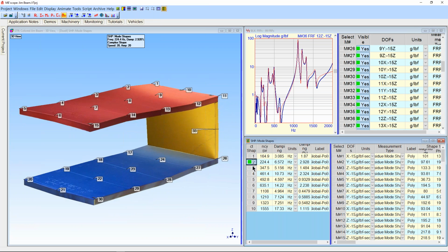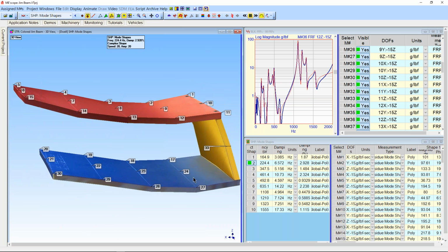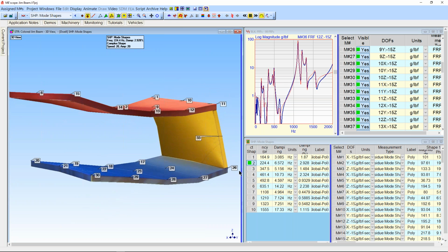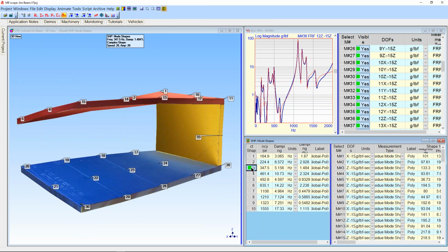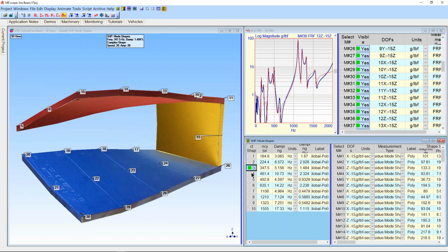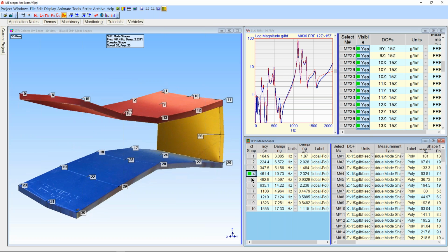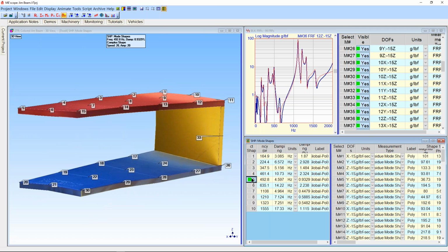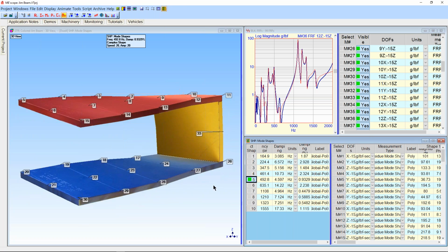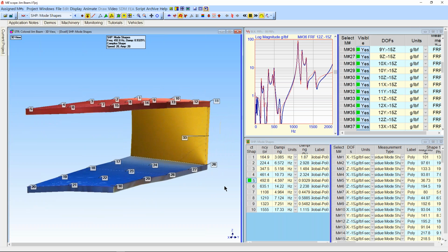And then bending, what I would call in-phase bending, where the top and bottom, I'm looking at first bending of both top and bottom. There's out-of-phase torsion. There's out-of-phase bending. So we can give these names, but pretty soon we run out of names. So the best thing is just to say, instead of the in-phase torsion, this is the 492 hertz mode.